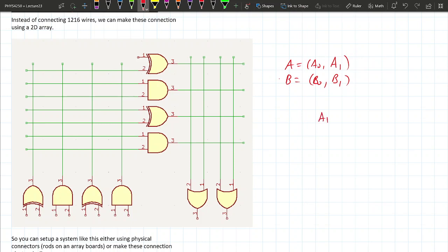And we want the outputs. So this is going to be A1, A0, B1, B0, and we're trying to add these numbers together, and this is going to be carry out 1, carry out 2. Since these are empty, they're always going to be 0. Remember, this is an exclusive OR between them, so we have an exclusive OR gate here, let's use this. We make this input A0 and this input B0, and that allows us to accomplish this operation.